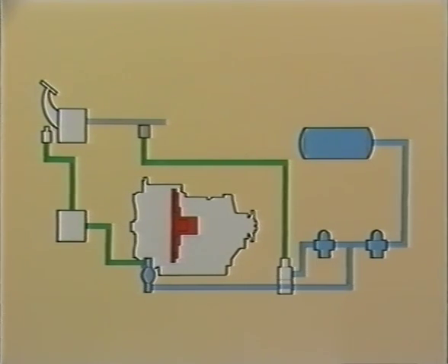On the assumption the initial test on the MV1 solenoid was correct, you must check the continuity of the cable from the MV1 plug to the panel plug on pins 21 and 24. If correct, check that the panel is receiving the switch signal from the micro switch. This can be achieved on the panel plug connections 27 and 24 with the foot brake applied. No response would indicate a wiring or switch failure. If all these items are correct, the control panel is suspect.